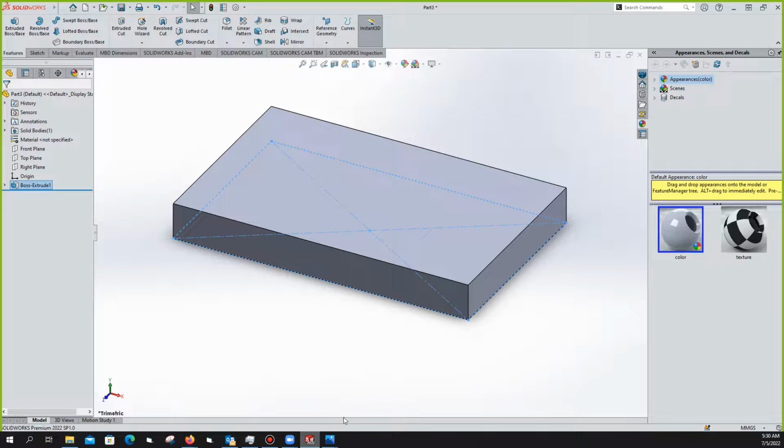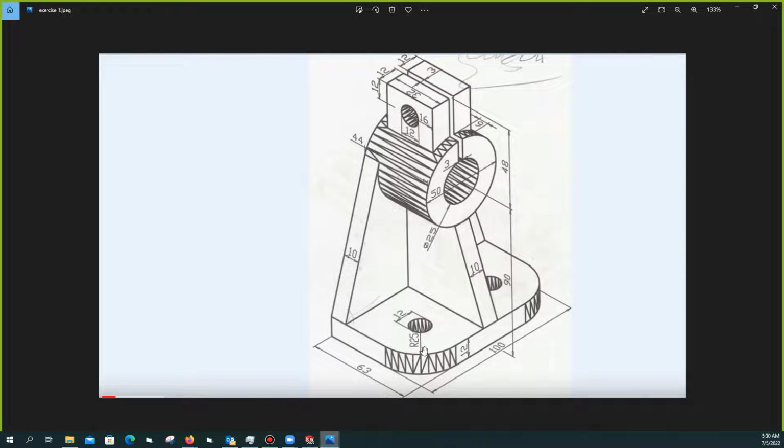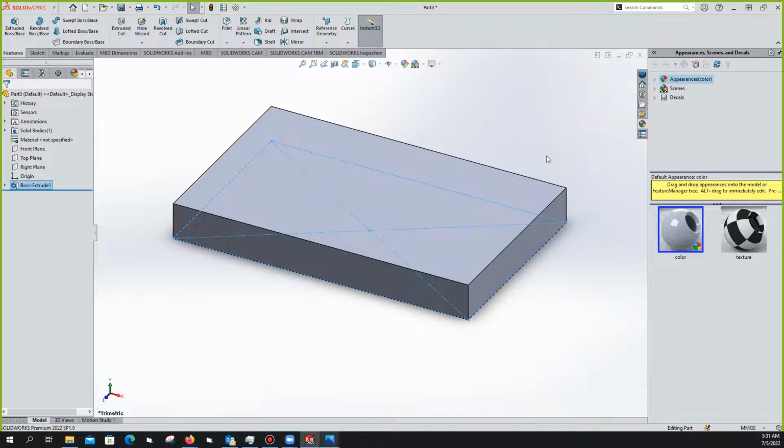Then after doing this, when you look at our design, it shows that there is this part is filleted. There is a command we call the fillet tool by the radius of 25. So you come, let me minimize this a bit. Okay, so we want to fillet these two. You can select both of them. Then you go to the fillet tool.